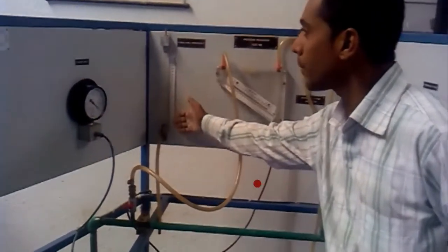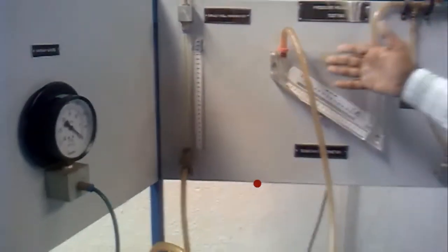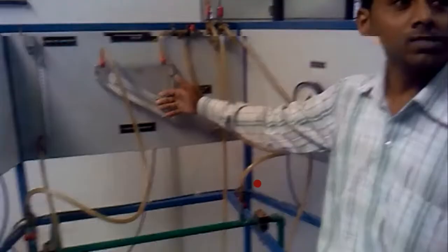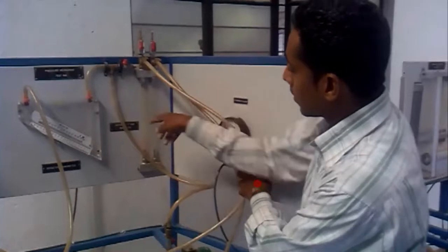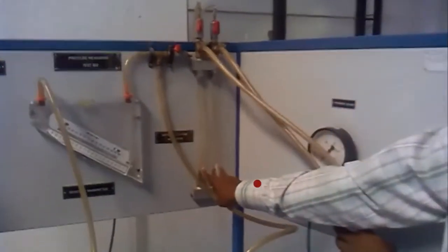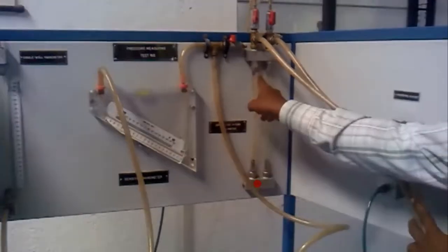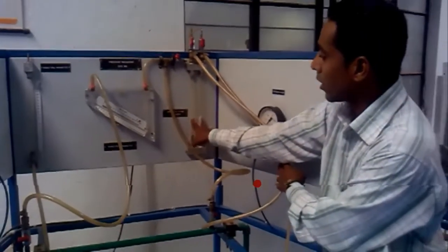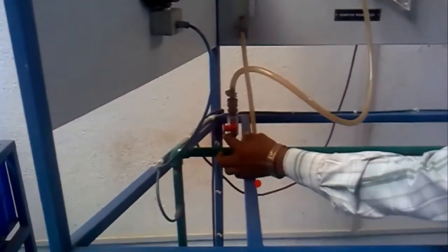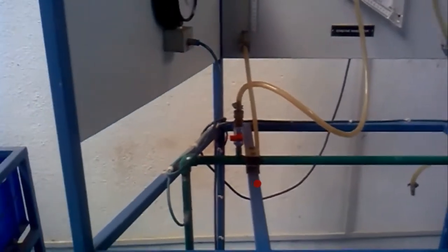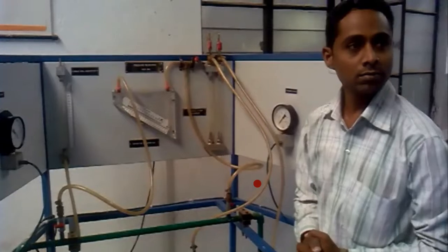This is a single well manometer. It has only one tube. This is a sensitive manometer, meaning inclined tube manometer. And this is a U-tube manometer. Two tubes, at the bottom they are connected to each other. We call them a U-tube manometer. Now, this we are using to find the pressure difference between these two locations. Here, we have two outlets in the pipe. That's why we call it a differential U-tube manometer.